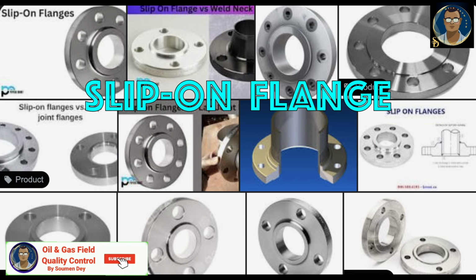Slip-on flange. It is widely used because of ease of alignment in welding. Its cost is also less. The flange is useful for moderate service process operation where temperature, pressure changes, vibration and shocks are not severe. Its strength is around 70% that of the welded neck flange, and its fatigue life is nearly 1/3 as compared to a welded neck flange. So the welded neck flange is much more secure and reliable, but it is costly. So for moderate and low pressure services, slip-on flanges and screwed flanges are used.